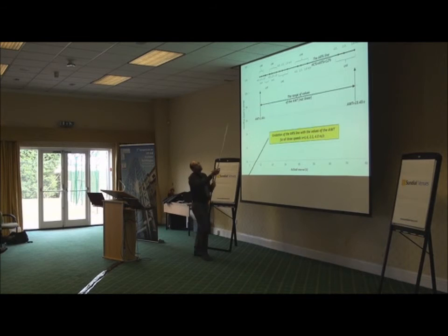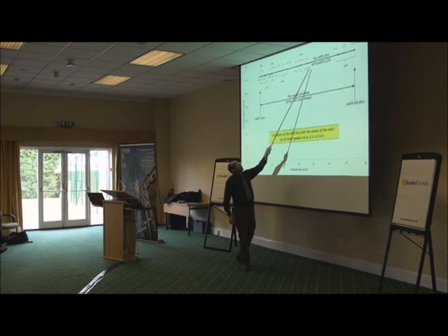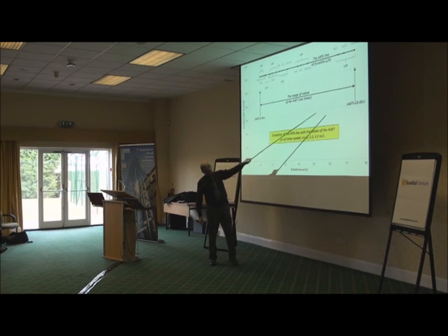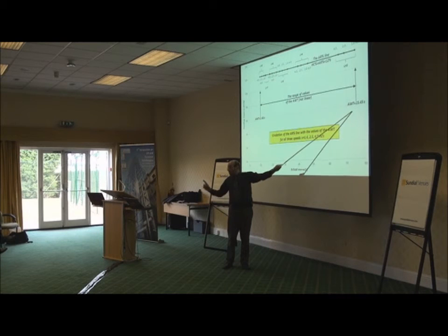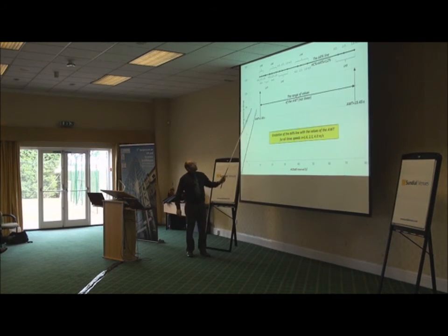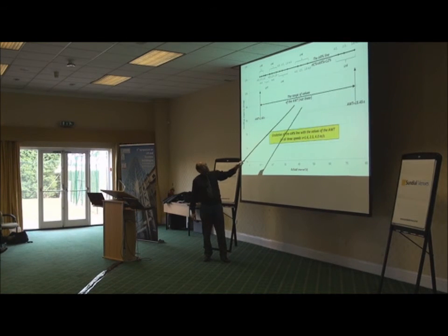So again, we have for 3 lifts the 3 speeds, for 4 lifts the 3 speeds, and each one of them has a value of average waiting time. And the average waiting time changes, not linearly, from 15.45 to 1.64. It's not a linear scale, because it has that equation in there. And then you can start seeing, in order to achieve a certain value of waiting time, where to stop.